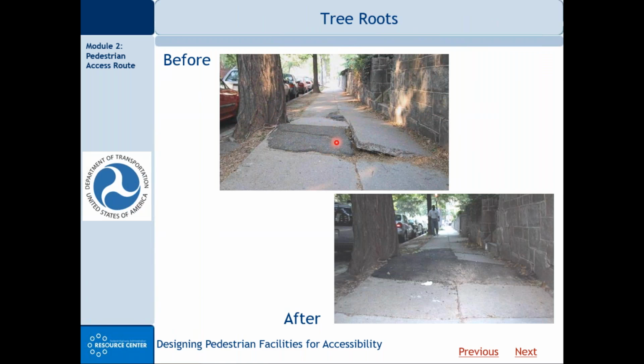What to do about it kind of depends. I've seen cities in the South where they have what they call live oak trees, which are very large and may actually intrude on the sidewalk, but they will build wooden ramps and a boardwalk over this area and then ramp back down to the sidewalks. That's considerable expense, both initial cost and maintenance expense, but that might be one way to make this accessible without interfering with the various constraints that we see in this image.